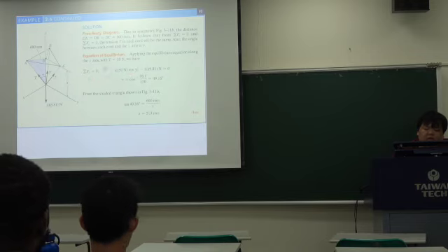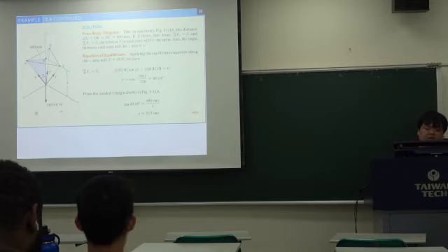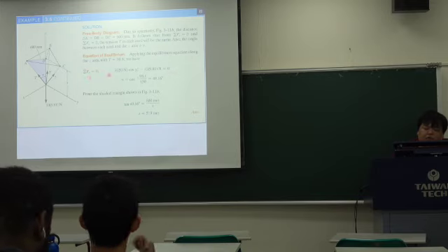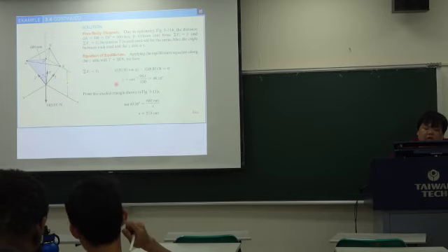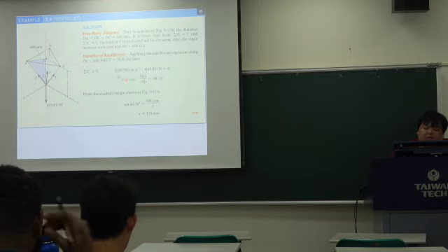Okay. Then we minus the loading force, so the loading force is equal to 10 times 9.81 Newton. Then the sum Fz is equal to 0. We get the equation. Then we can calculate the angle. Gamma is equal to 49.163 degrees.